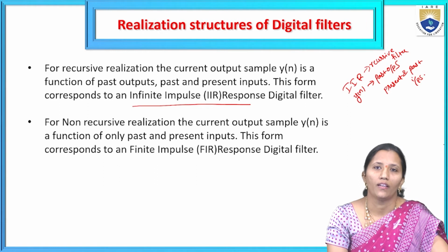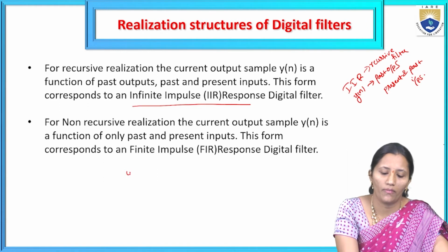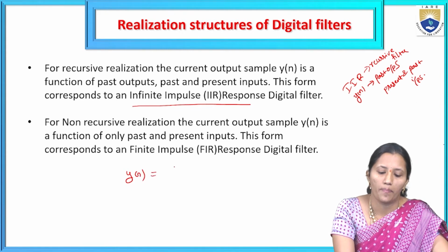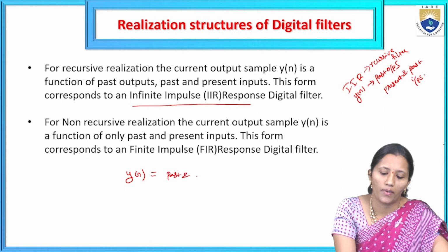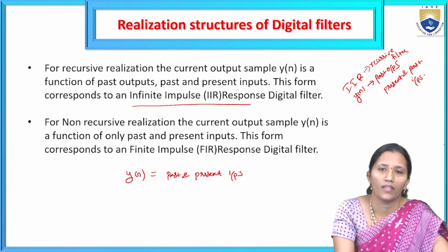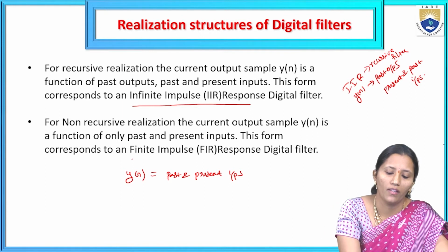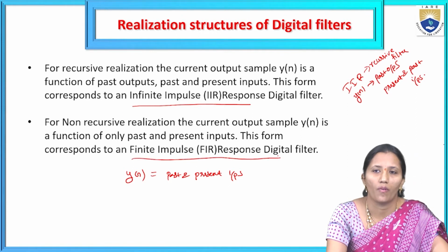And for non-recursive realization, the current output sample y(n) is a function of only past and present inputs. It will not depend on the past outputs. This form corresponds to the finite impulse response digital filter.